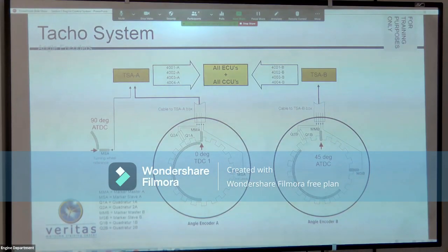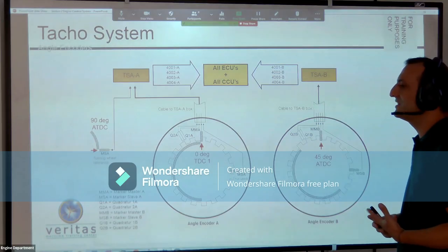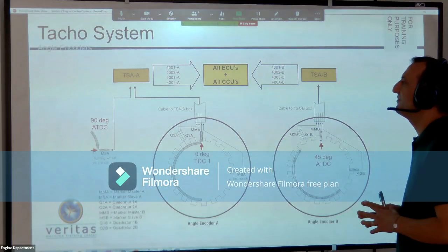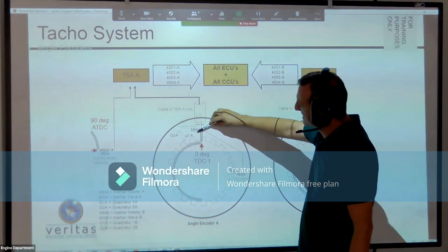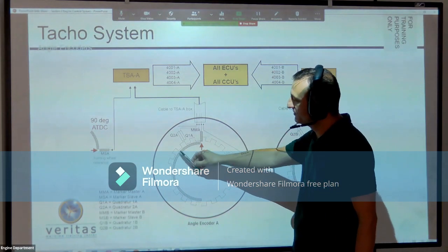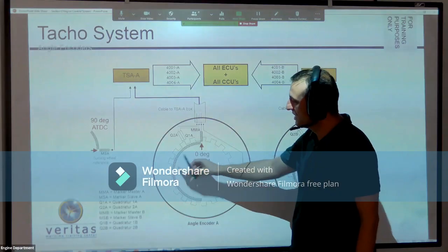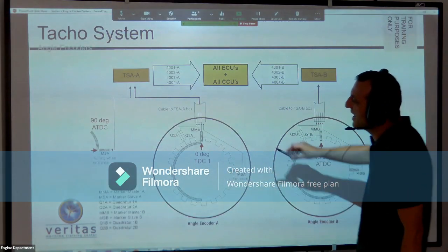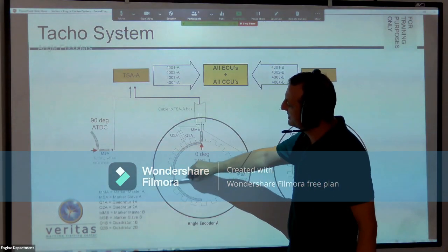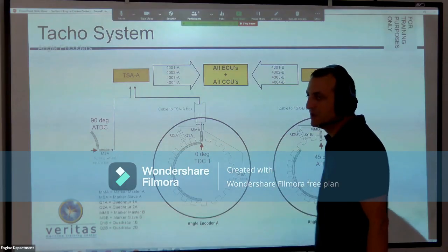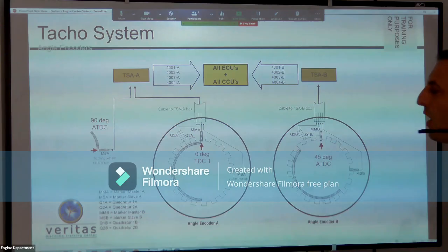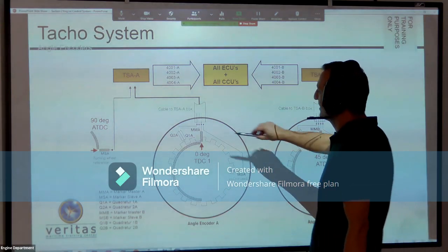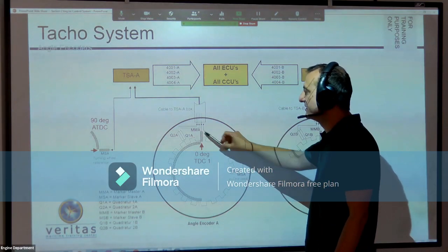What is the difference between the sensors? The sensors are similar, but the difference is that they take the reading from different parts of the hollow shaft. The marker sensors take the reading from the semicircular ring. The quadrature sensors are activated by the 360 teeth ring. So gentlemen, per 1 engine revolution, how many times will the marker sensors be activated?